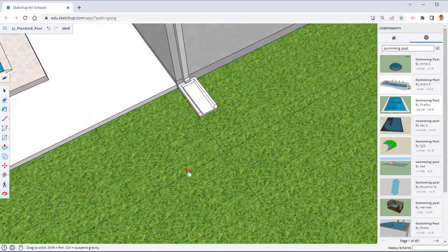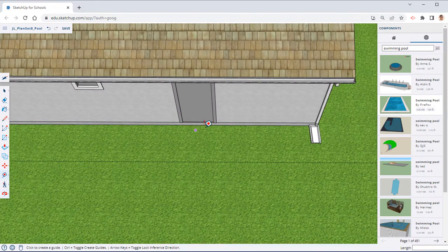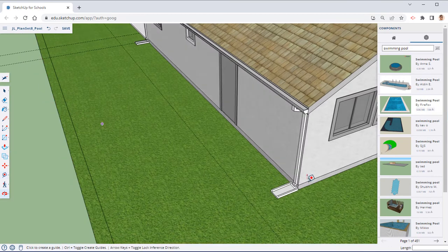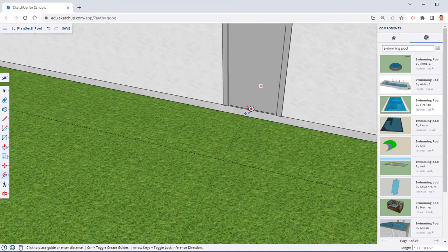So it comes down through here. It cuts there at the center of our door, goes over 6 feet total, and then goes down to the sidewalk. So let's use our trick to find the center of our door. Again, hit your left arrow key, move your mouse up to find that 11'6". Go ahead and click. We're going to go to each side 2 feet.